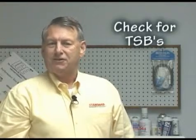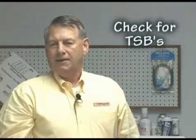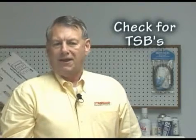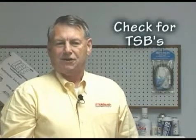We return to the office and check for technical service bulletins, because in the past, General Motors has recommended that if a blower motor control module is faulty, you replace both the blower motor and the blower motor control module as a unit. Upon checking TSBs for our 2006, this is no longer recommended.